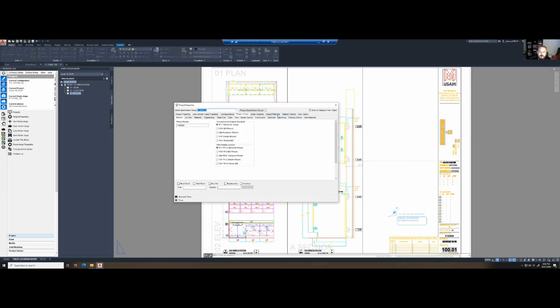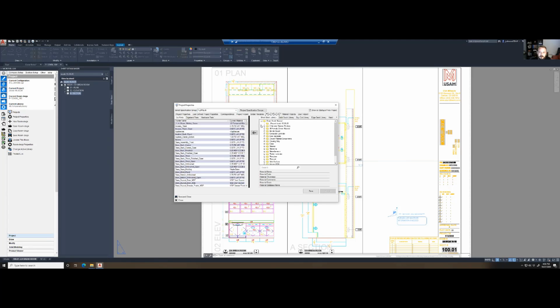So we go to our materials, you'll notice there's nothing here in the project materials folder. And so the typical way most people will use this is you'll come in here, you'll come to your PL1, and you can find and replace and say, okay, PL1 is now 4248.